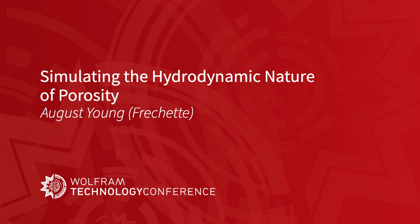So we are going to be discussing the hydrodynamic nature of porosity. And this is really quite foundational. Normally porosity is just assumed to be a constant in any porous media. And there's a term called effective porosity, and that just means what part of that empty void space in your porous media is conducive to flow. Well, we're going to show that that effective porosity is flow dependent, meaning as you increase your flow speed, you're changing your effective porosity.